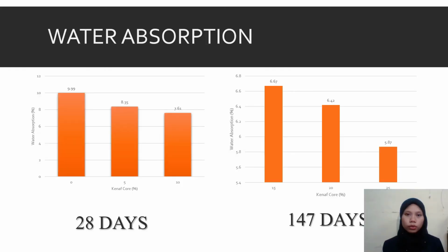So let's move to the water absorption test. For water absorption, it's the same as the flexural strength test, and I tested on the 28th and 147th days. And from the result, we can see that the increase of the Kenaf core replacement will decrease the water absorption.